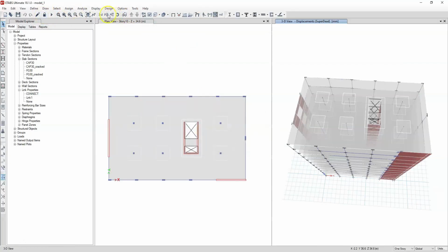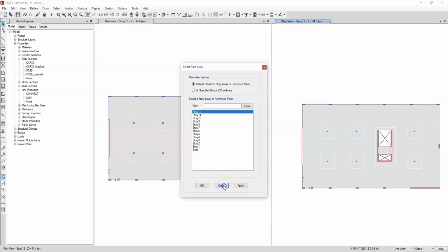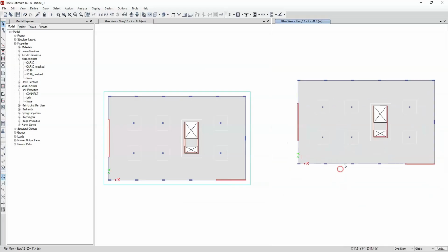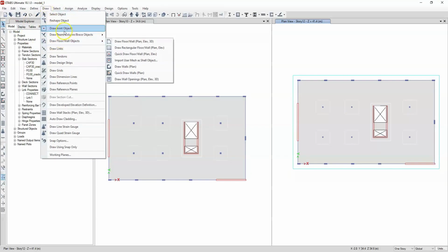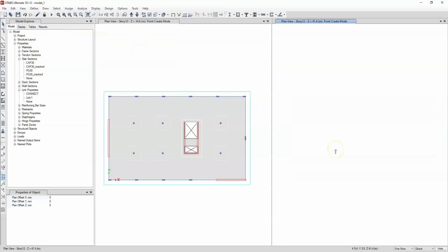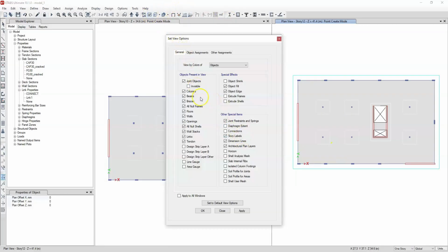We are now going to continue with the next steps. We are going to create a joint in the structure, which is the joint where we are going to apply the forces used to measure the stiffness of each story. We are going to draw a point using the ETABS editing tools. We look at the created joint.